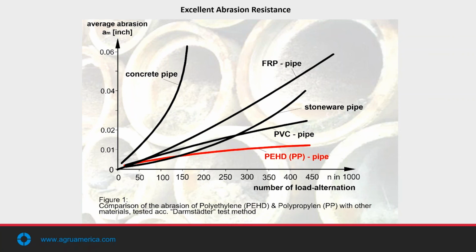And there's a slurry or a solution placed in there with an abrasive slurry material. And then that trough is tipped on one end, causing the material to flow or slosh down to the other end, and then it's tipped the other way.